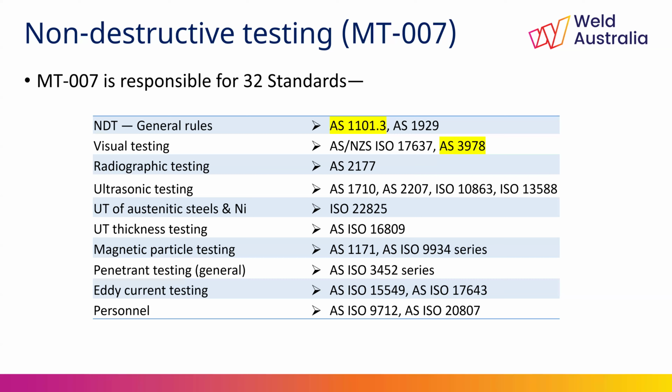Okay, this one's a bit longer, so bear with me. Is there a consensus with the audience regarding hardness failures with overseas materials, particularly GR 350 grade, that is typically higher CEQ value, primarily China and Korea exports? From my experiences, I have been challenged numerous times on this issue, even with significantly increased preheat levels. It is time we have government bodies imposing Australian steel content to some degree as mandatory for projects in Australia. Okay, can I hold that one over to when we get to the end of the proceedings, and I'll address that at that point.